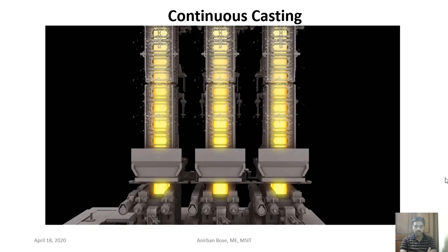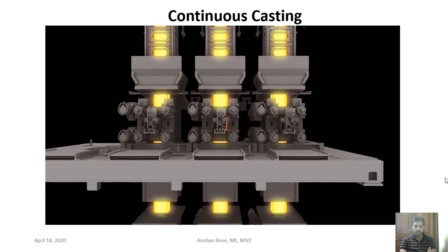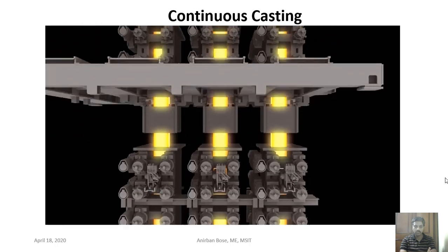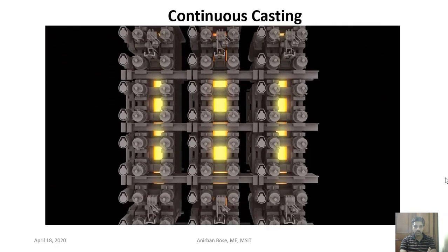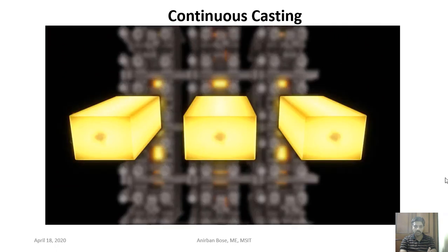Between the rolls, we use air mist sprays to cool the bloom surface and strengthen the solid steel shell. Below the segments, a series of large rolls support the strand. Several of these rolls can apply soft reduction, which is a slight squeezing of the bloom shortly before full solidification. This provides the bloom with a superior solidification pattern and minimizes carbon segregation.